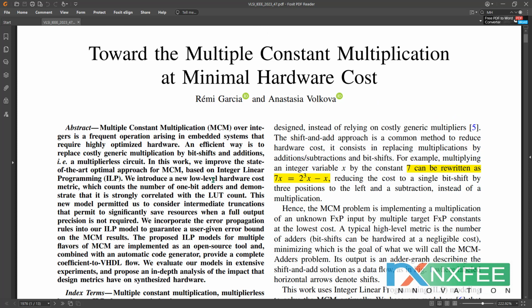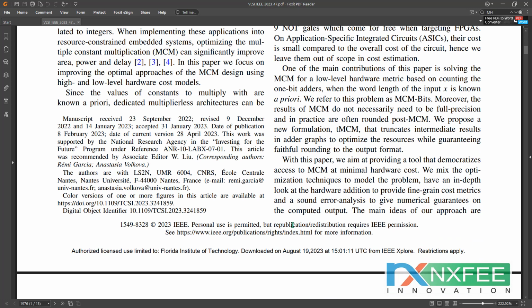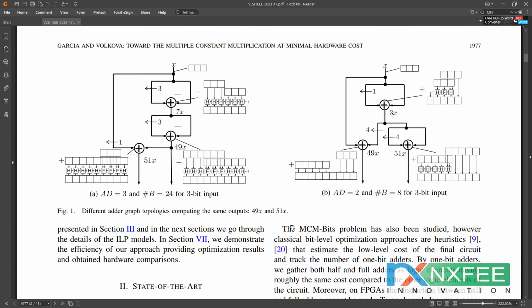This paper does not use any multipliers. Instead of multipliers they use shift registers and adders, so based upon the shift registers and adders we can eliminate the multipliers. Multipliers take a larger number of logic cells compared to shifting and addition operations. Why? Because an 8 by 8 bit multiplication will take 64 partial products, and for these 64 partial products we need to use a number of full adders.